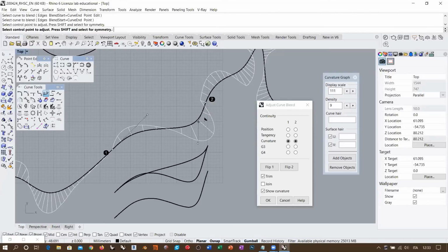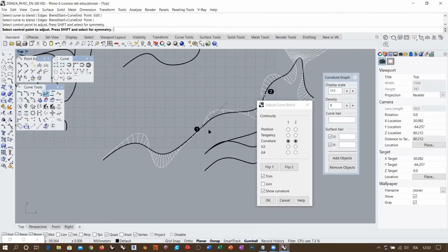There is no, as we were drawing this NURBS curve by hand, like using a control point curve, as I told you, this is a degree 3 curve. By default, Rhino doesn't create a non-uniform knot vector. And there is no possibility to create coincident control points. So there is no way that this curve here has some internal discontinuity, right?